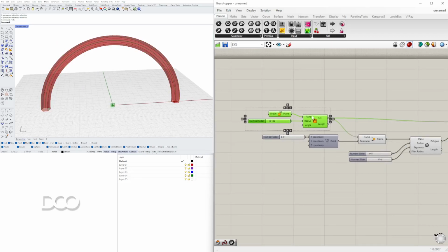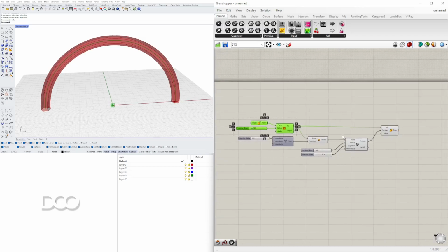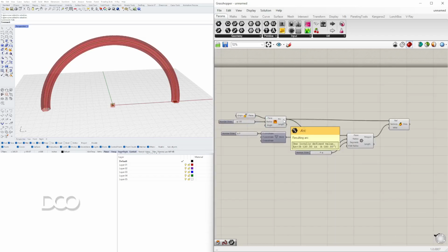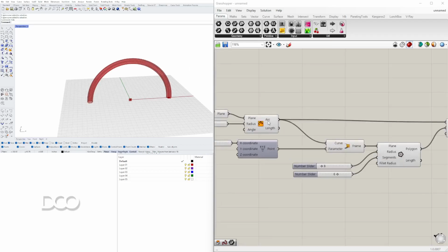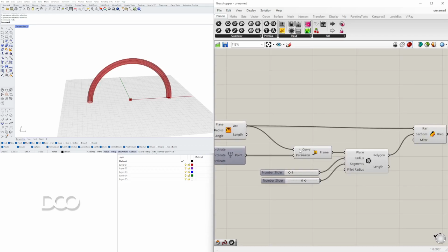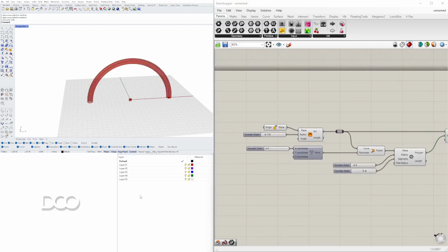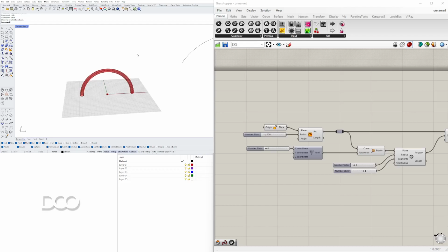Now, one of the techniques that I want to share is that if the idea for the script is to be able to change any curve into a segment like this, then you need to keep in mind that we have this arc output going into 2 different inputs, and it's a lot cleaner to have one output go into this one and one go into this one. This way we can change the arc, and this is why I have here, if I do show, a different arc segment that I created using a spline or a NURBS curve.